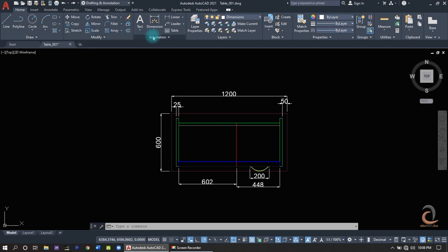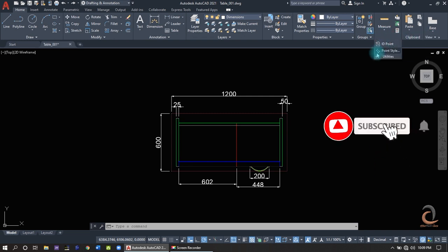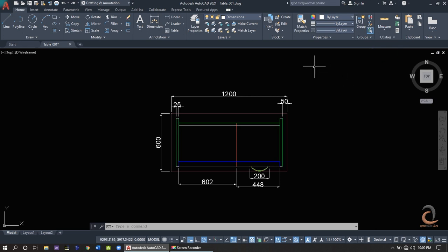The Home tab consists of the Drawing panel for the creation of geometry, the Modify panel for making changes to the geometry, the Annotation panel for creating text and dimensions. There are many more like the Group panel for grouping objects or drawings together and more. Also, apart from the Clipboard panel, every other panel has a drop-down button, displaying more content anytime you click on it. You can also pin and unpin the content at will.